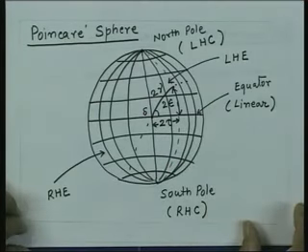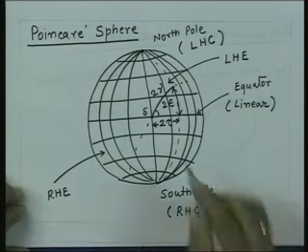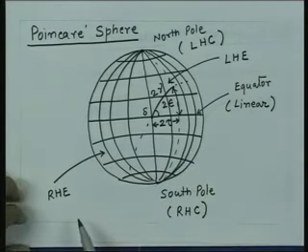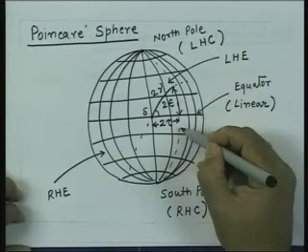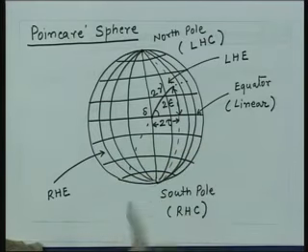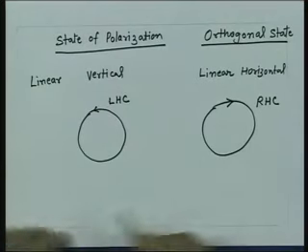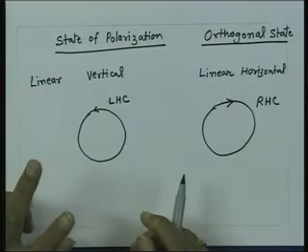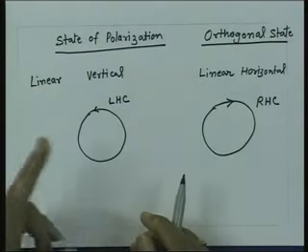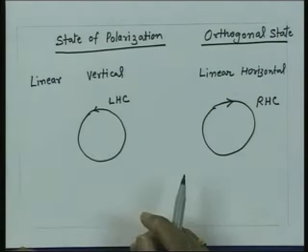What that means is that the tilt angle of the ellipse is changed by 90 degrees because 2 tau is changed by 180 degrees, and epsilon remains same, that means the axial ratio remains same, but its sign changes because I have a diagonally opposite point. So, any two ellipses which are having same axial ratio but opposite sense of rotation and tilt angle differed by 90 degrees will represent orthogonal states of polarization.